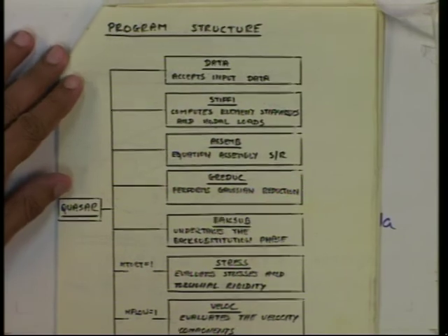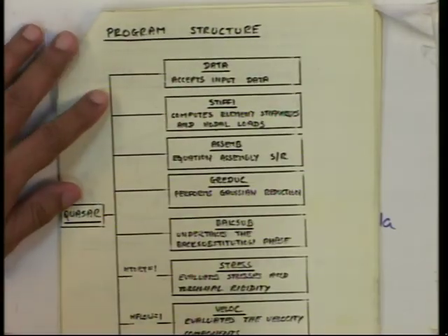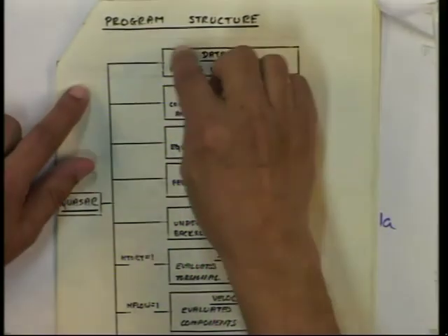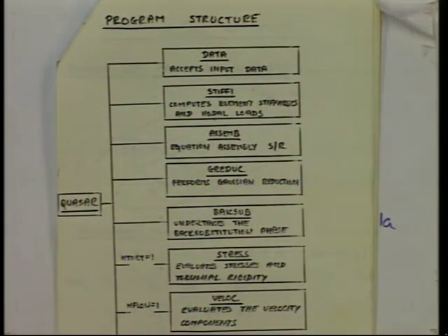Any finite element program will always have first one subroutine wherein all the data will be input. We input all the data, meaning geometrical, material, node numbers, coordinates, all these things have to be properly read. I am talking of a research program for understanding, not a commercial program.